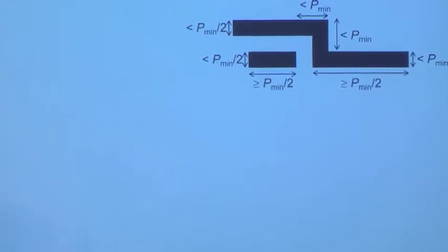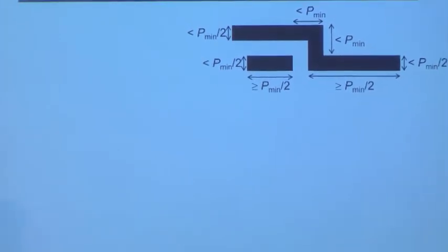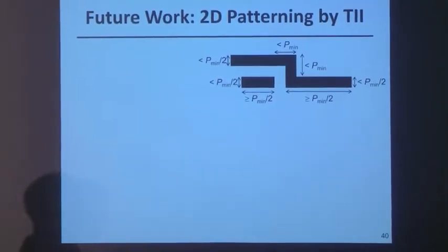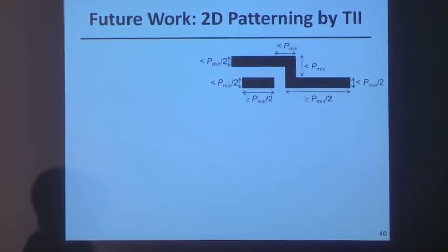So what I'd like to do next, though, is really apply this technique to further reduce the cost more drastically. So today, the most advanced chips have over a dozen layers of metal, right? So the metal layers that have the tightest pitch, the metal lines are only running along one direction, and then the next layer, in the orthogonal direction. So if you want to connect a transistor from one part of the chip to another part, you need to go through multiple layers of metal, right, running horizontally and vertically across the chip. And the reason that the industry had to do that is because of these sublithographic patterning techniques.